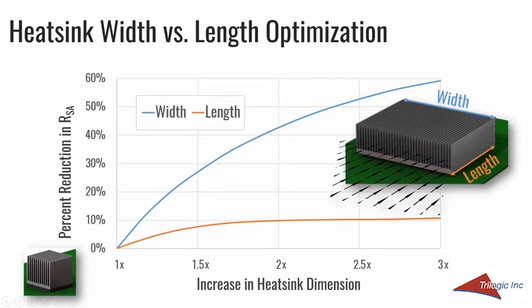Width, I have much larger benefit in going with width, but it's not linear. I believe that if this heatsink were a perfect conductor, this heatsink width would probably be a linear variation. Let me know if you disagree or have other ideas, and we can explore them and write about it.